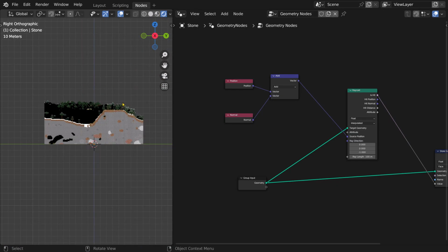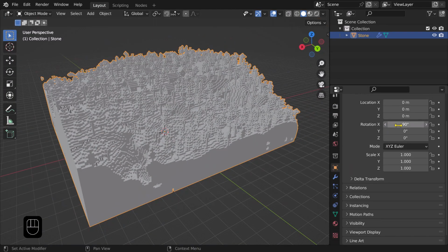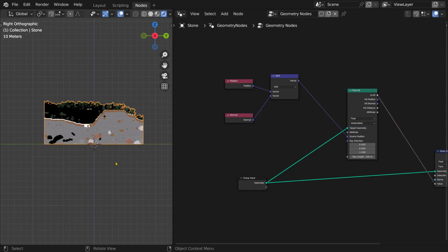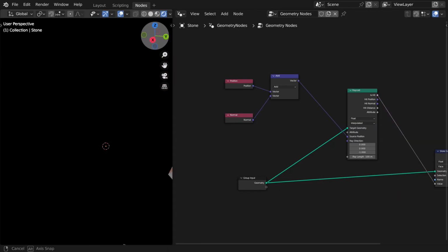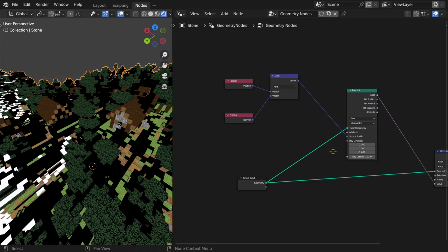Well, this was supposed to be solved easily. But if you notice in the settings of this shape or object, you will see that the world is flipped by 90 degrees on the x-axis, and this is what made the light direction wrong. Therefore, this needs to be fixed inside geometry nodes.